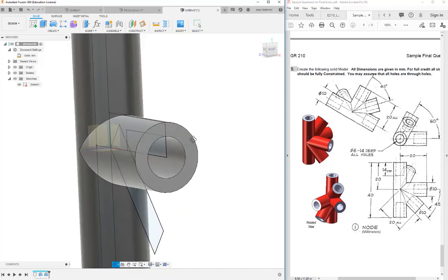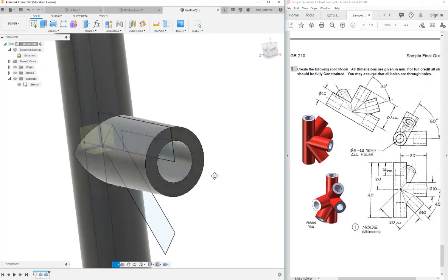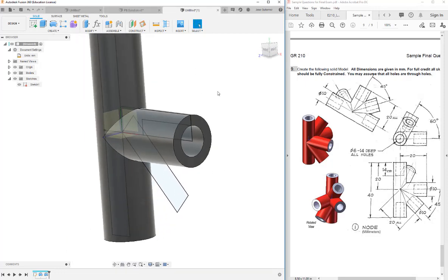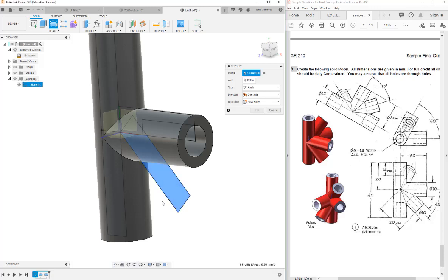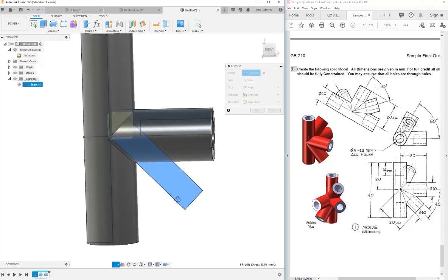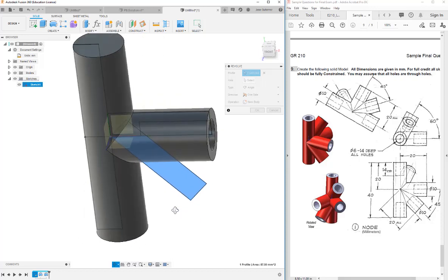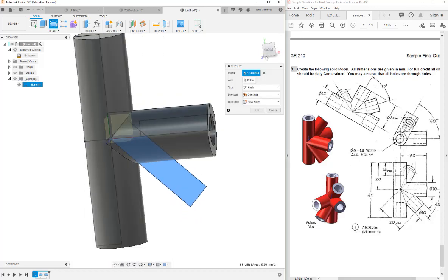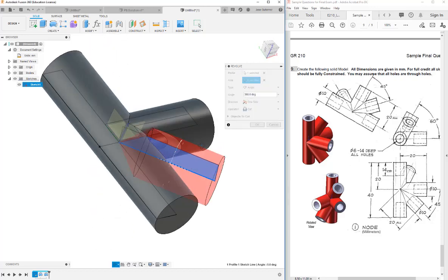And you see by omitting that profile right here, I did get this blind hole. Now we'll go ahead and use the hole tool for the other ones. And I'm going to go ahead and repeat my revolve. And what I'll show you here is if I don't select the right feature, and actually if this fully, let's see, this might not work. So that's given it its own axis, and yeah, it will not work.